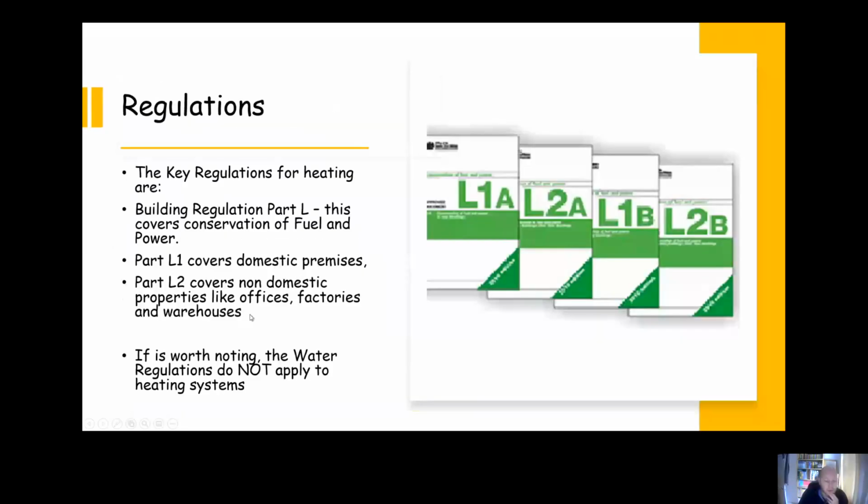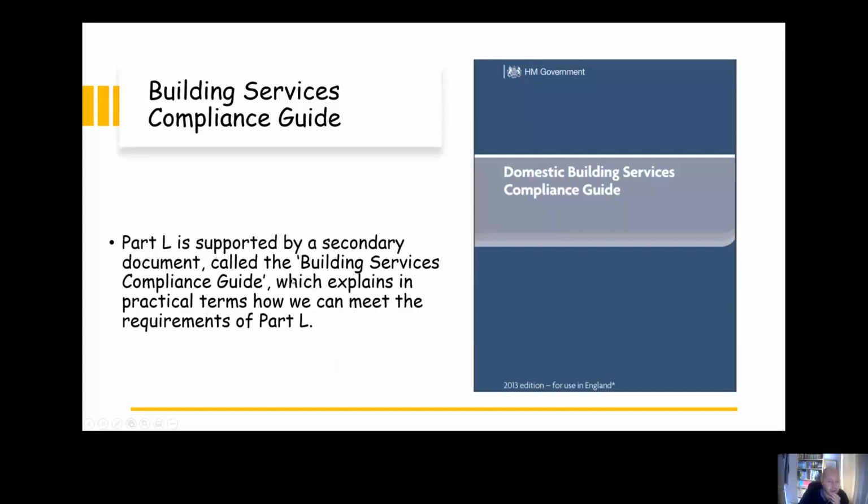Okay. Worth noting, water regs don't apply to heating systems, apart from obviously where the mains connects into the system. We need to make sure you use appropriate backflow, but apart from that, the actual heating system itself isn't governed by the water regulations. Building Services Compliance Guide.